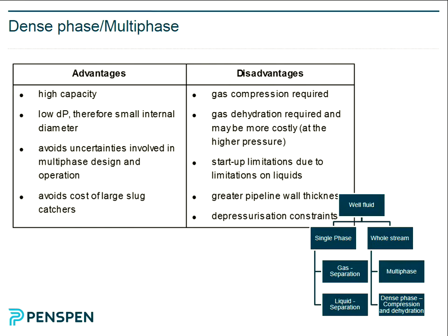And liquid holdup. If you think about a pipeline, when you're producing multi-phase flow, you can actually work out how much liquid is held up in that pipeline. So you've got gas and liquid at the same time. The hold-up is that total liquid, and also there's the individual hold-up. So you can consider it section by section, because it will vary along the line, or the total hold-up.